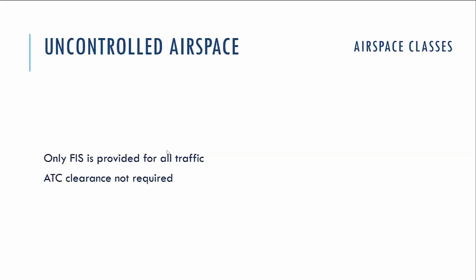Uncontrolled airspace, I think, is the most common and more interesting for VFR pilots, because it's the basic airspace where you can fly without any clearance and without filing a flight plan. So only the flight information service is provided for all the traffic in the uncontrolled airspace, and as we said, ATC clearance is not required to enter the uncontrolled airspace.